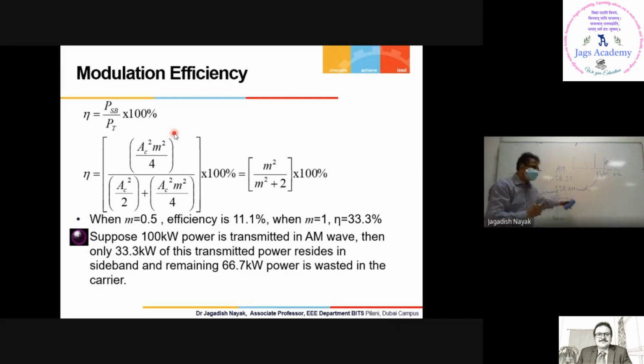This equation will not have any carrier component in that. Okay. Now after that, it will have lower sideband, upper sideband. Once again, two sidebands. You have to remove one sideband. So once you remove that sideband, it will become single sideband AM wave. So that is to be highly efficient because only one sideband is there in your transmitted AM wave. Right? I understood this. Okay.